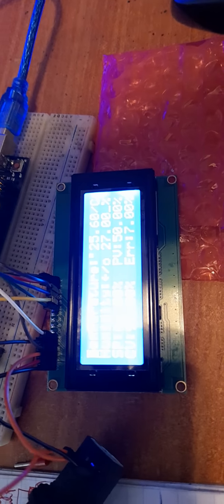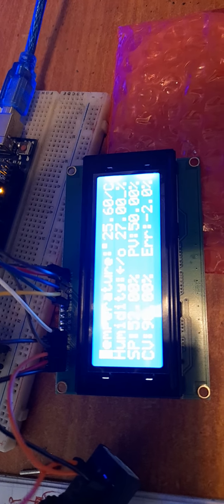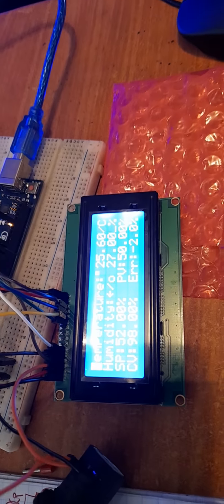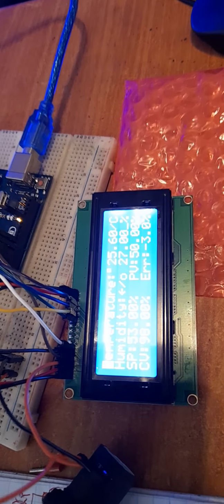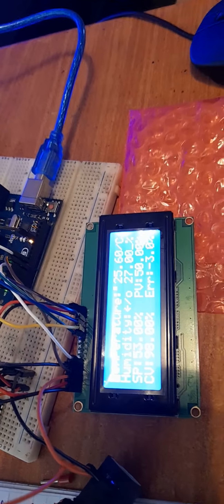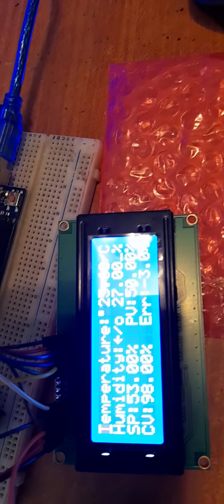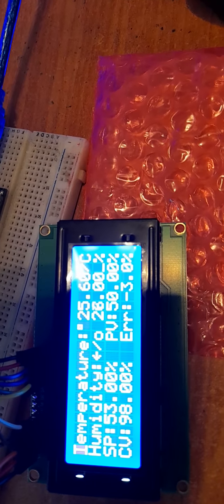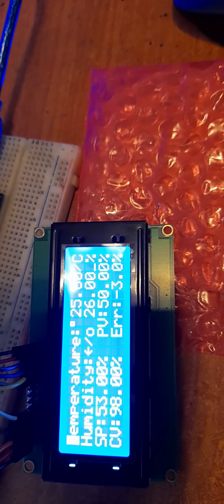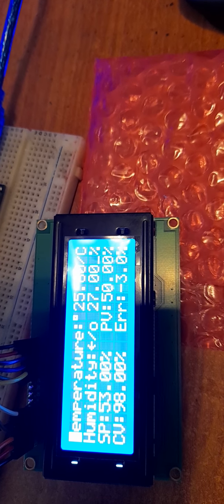7. Let's take the error to the negative by increasing our control system set point. If the error is negative, the PID must start closing, meaning slowing the motor speed down. It's going to be dropping from 98, then go to 97. It's going to go slowly because the error is so small. Let's increase the error by increasing our set point.